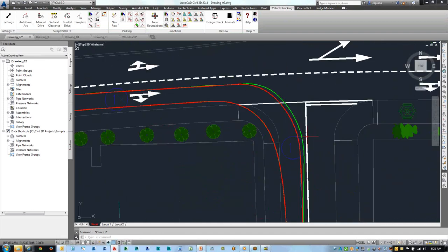Okay, so likewise over here, I want to point this out. As I enter the turn, I'm proceeding over the top of this curb. I want to point out these little arrow grips here. It's a side overturn. So both at the entrance of the curve and at the exit of the curve. So I can select that particular grip, and then you can see me adjust the particulars of that turn. So maybe the vehicle would not be able to turn into this particular entrance without steering into the oncoming traffic, certainly at slow speeds.